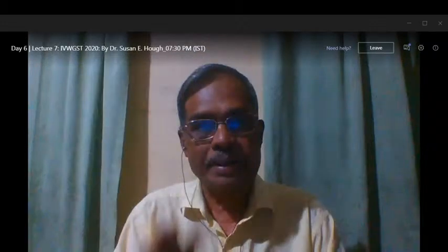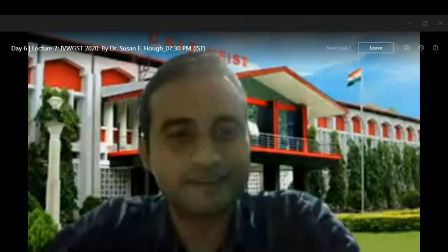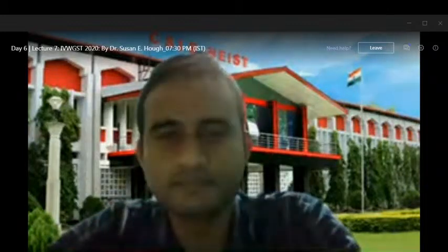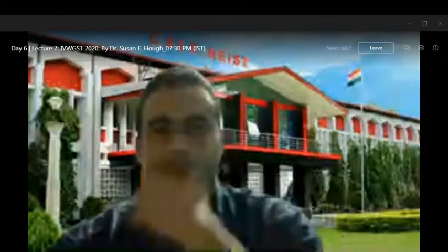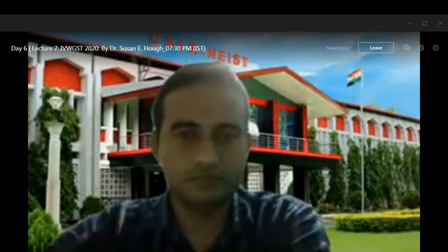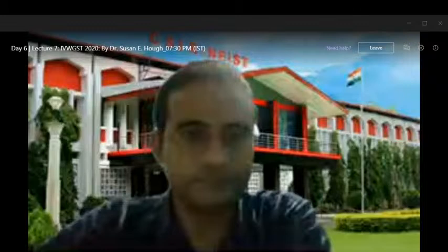There is an important implication here. You have this long period site response, say, in Kathmandu or Ridgecrest. In Kathmandu, that shaking would have been damaging to a 50-story building, but there are no 50-story buildings in Kathmandu. In Ridgecrest, shaking would have been damaging to a 30-story building. So there is an opportunity: if seismologists can understand this long period shaking, it leads to a recommendation that you limit building heights. You don't want to start building a 50-story building in the Kathmandu Valley for the next earthquake. It's good to keep the structures smaller.